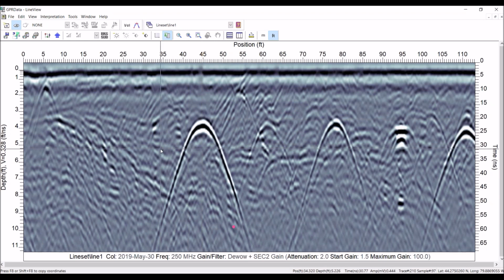So we need to plot a depth axis, and the depth axis appears on the left here. And it's obviously way more understandable than the time axis. Many of you will know that to get the depth axis, we need to convert our time measurements to depths. So how do we do that? Remember the velocity calibration you do out in the field? Remember fitting hyperbolas so they match the shape? When you do this, you are measuring the velocity of the GPR signal in the soil. And it is that velocity value that is used to convert the time scale to a depth scale.